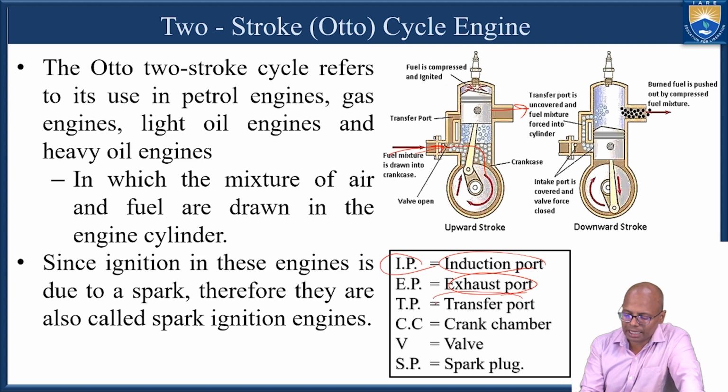Now, what is this transfer port? The transfer port is the one through which the slightly compressed air fuel mixture is allowed inside the cylinder. So this air fuel mixture from the crankcase is passed into the cylinder through this transfer port.